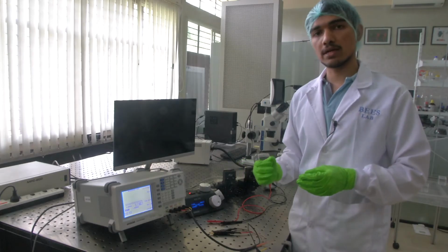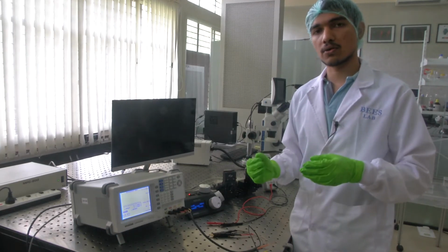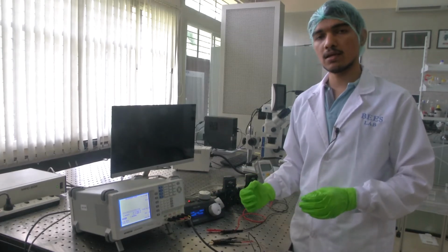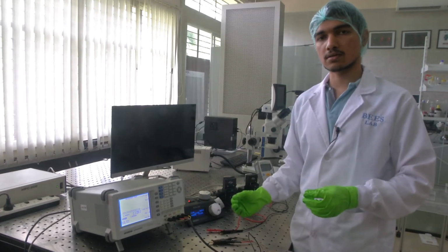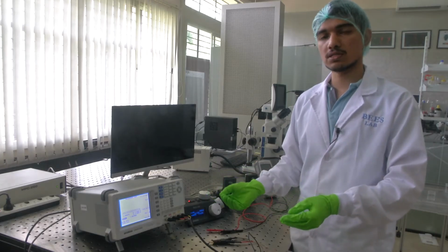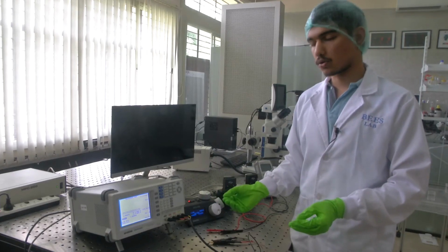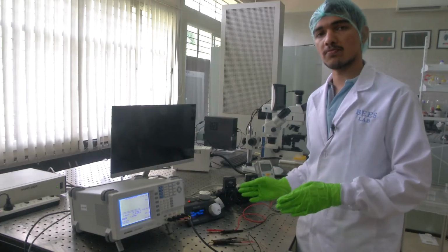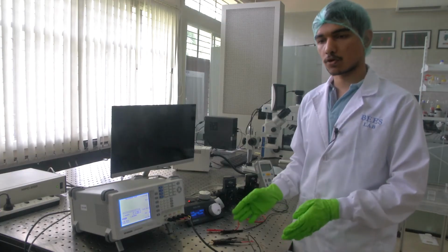So, we avoid the contact resistance or the contact loss in the sensing. Whatever value we get will be free of contact resistance, and whatever impedance measurement we get out of this will be accurate. Okay. So, that is the difference between a 4 probe and a 2 probe. 2 probe will be less accurate compared to the 4 probe measurement.